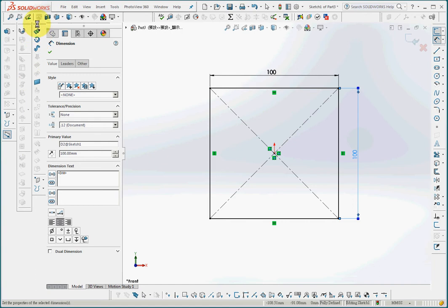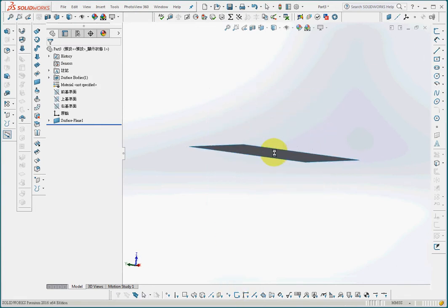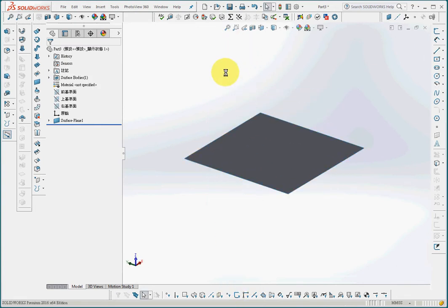On the surface toolbar, choose planar surface. I'll make the geometry as simple as possible so we can concentrate on the CAE analysis. This problem is a composite panel, an 8-layered carbon epoxy composite. So the material property is the most important part.